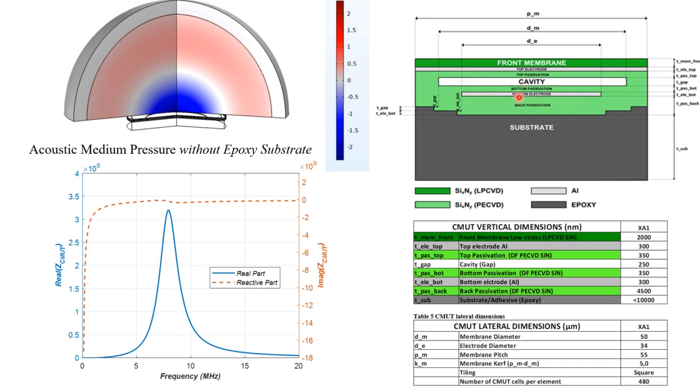If you consider this, the frequency comes out as a function of the geometrical and material properties we are giving in COMSOL. The 7 megahertz implies that your wavelength in water is a little more than 0.2 mm.